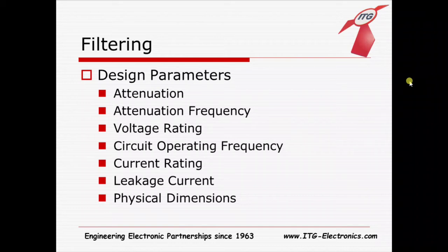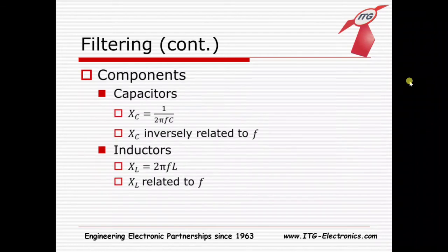And then finally, the physical dimensions are obviously going to be important in designing a filter. If you have a lot of space, you may want to utilize more of that space to get increased filter performance, maybe add another stage onto the filter, add some more components into the filter. But more often the case is you have very small space and you have to work with what you have. So being aware of how many stages or what kind of components you can fit into a given space is going to be obviously very important in designing it.